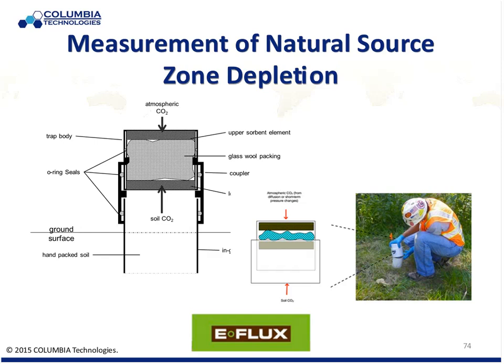It is quite possible that if I'm not moving and I'm not recoverable, I'm depleting faster than I'm going to be able to be recovered with skimmers and wells, particularly if those wells aren't screened in the right intervals, et cetera. So one of the diagnostic evaluation tools that adds to this LNAPL management issue is what is the off-gassing or the natural degradation state, what's going on.